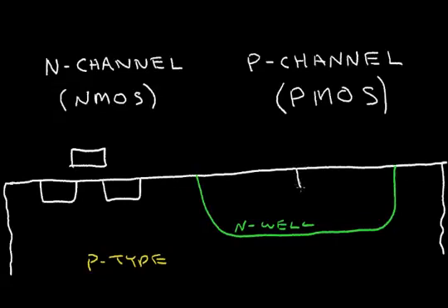Now the PMOS transistor has a similar structure. It has a diffusion, but this diffusion is a different type of material from the NMOS transistor. There's a gate like the NMOS. And there's also another diffusion that will go here, and this diffusion will connect to the well. There will be a diffusion out here that connects to the substrate.